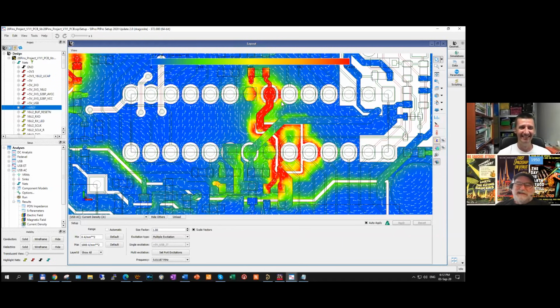And this is the concept that we all learned in elementary school and high school, and that was the basis of how we thought about currents in circuits. And that's okay for DC. Everything that we do at DC, that circuit model is just fine, really easy to understand. It's when we try to extrapolate that simple model into anything above 10 kilohertz, 100 kilohertz, that's where it breaks down. And so anything related to noise due to the current paths is affected by where exactly the return current is and when it is flowing.